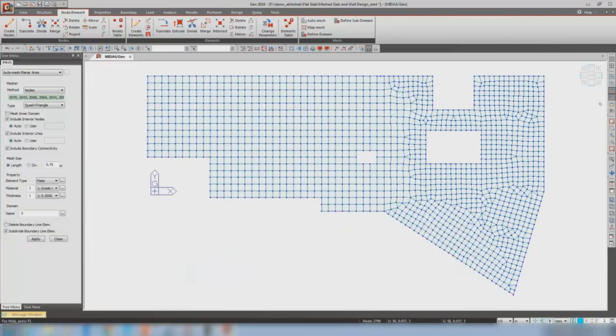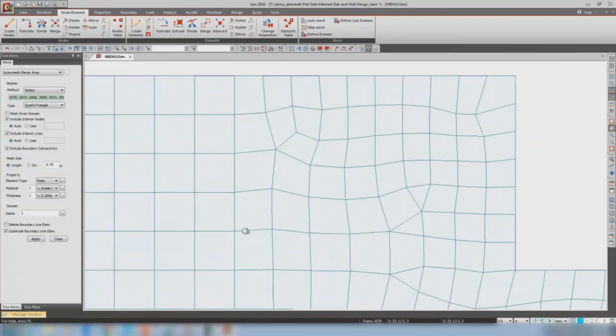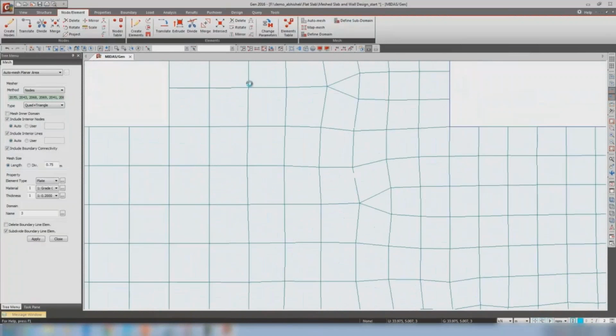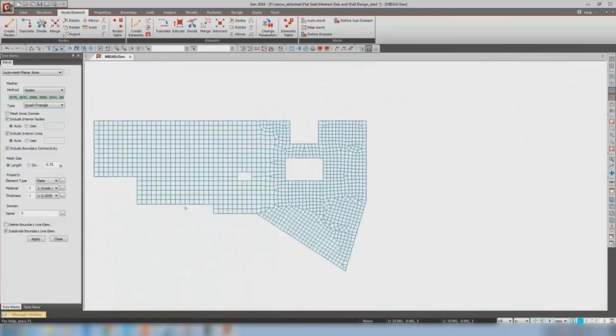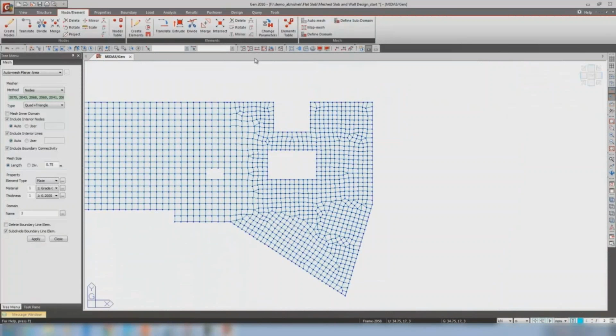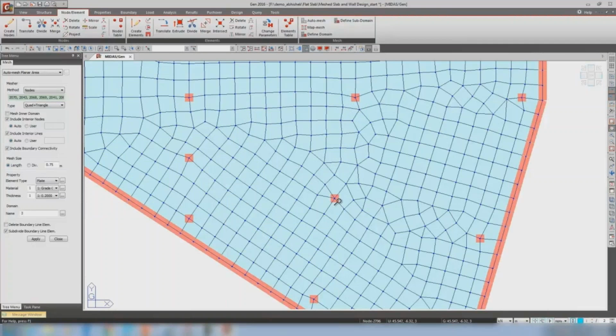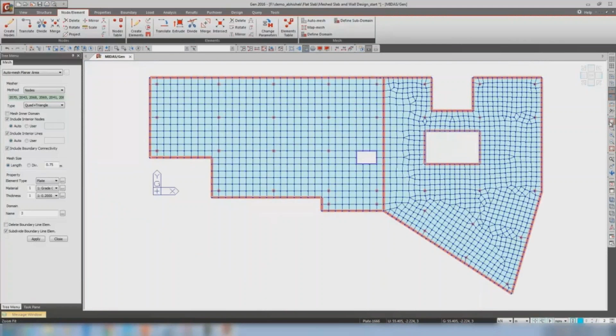I just click on the top view. Now you can see all the joints are passed. And if you see the irregular areas like these, I just open my hidden options. Now you can see the extrude view. All the columns are passed from the meshing. So meshing will pass from the column node so that it will not give the load transfer error. The entire thing will be minimized. Means by using the auto mesh option in Midas, you can save a lot of time.